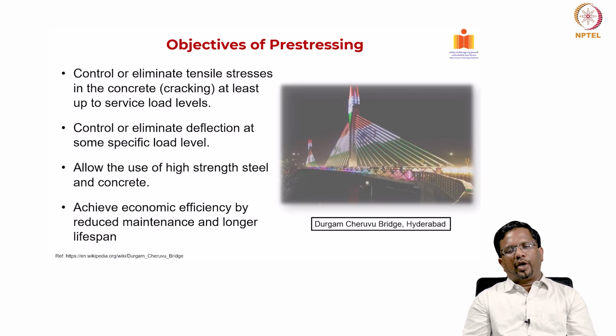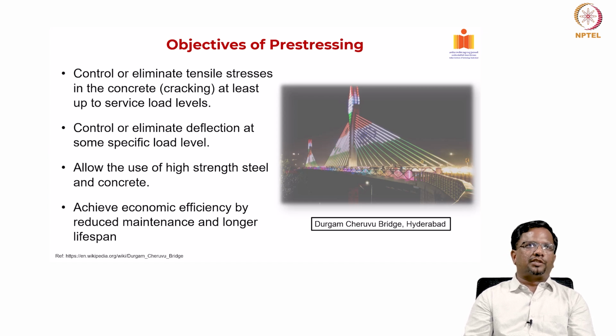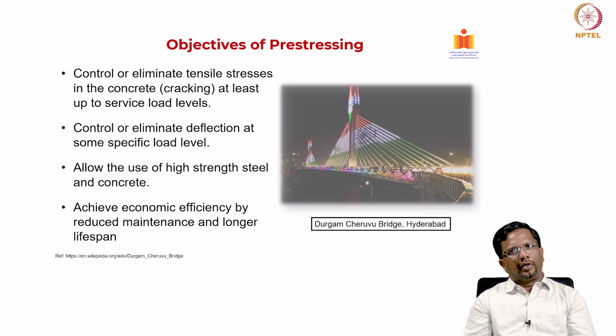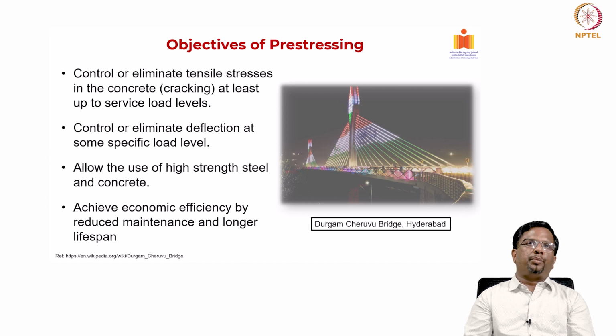Okay. Now, why do we really need to go for pre-stressing? So, our objective of pre-stressing is basically that concrete does not want to be in tension. In fact, if you are preventing the concrete from cracking, then you are basically improving the durability of the concrete.